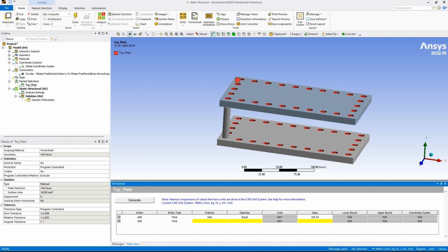The first line in this command is selecting all the holes. In the second command, we are subtracting some holes from that, or specifying something. Either we can use a filter, where based on the filter condition it will choose some holes from the top plate, or we can remove some from the top. So let's use the filter for now.